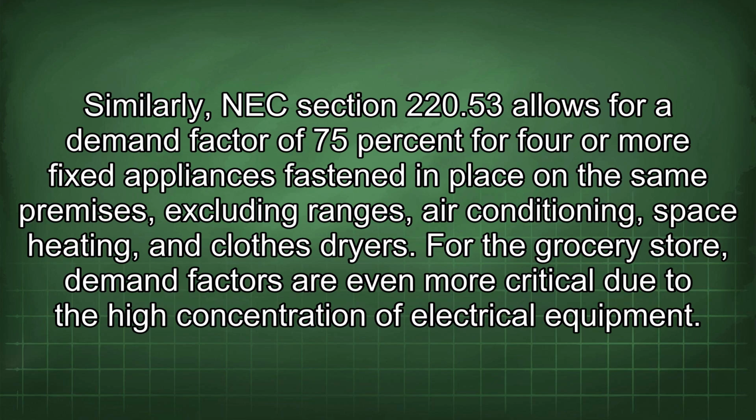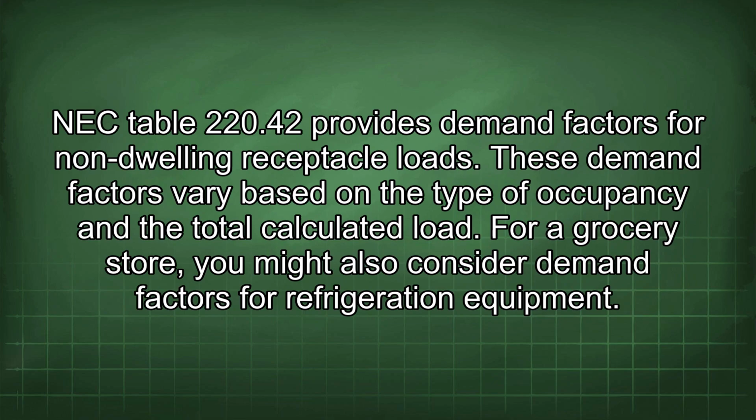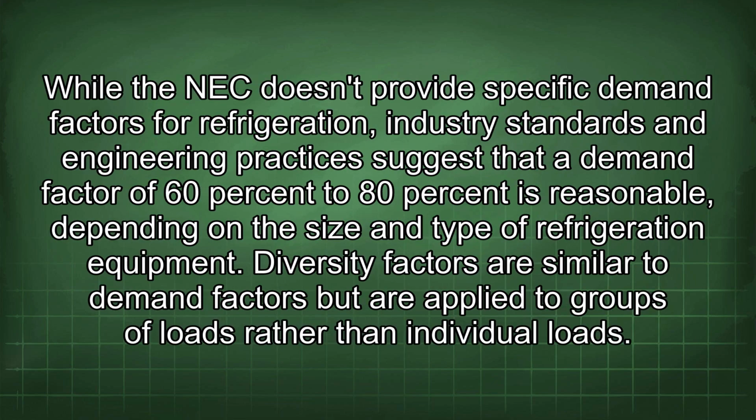For the grocery store, demand factors are even more critical due to the high concentration of electrical equipment. NEC Table 220.42 provides demand factors for non-dwelling receptacle loads. These demand factors vary based on the type of occupancy and the total calculated load. For a grocery store, you might also consider demand factors for refrigeration equipment. While the NEC doesn't provide specific demand factors for refrigeration, industry standards and engineering practices suggest that a demand factor of 60% to 80% is reasonable, depending on the size and type of refrigeration equipment.